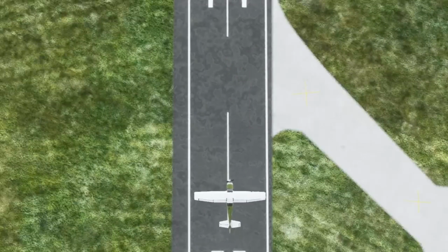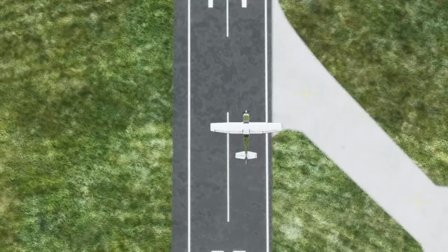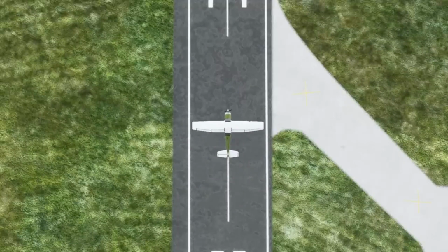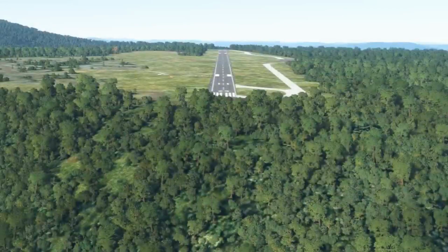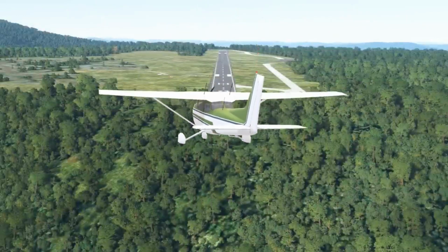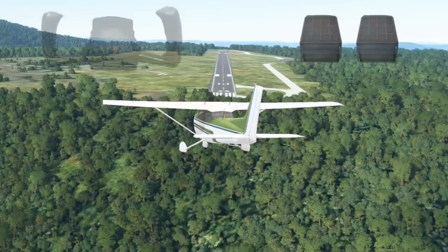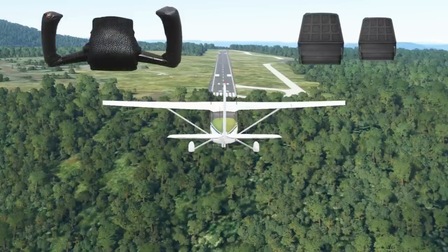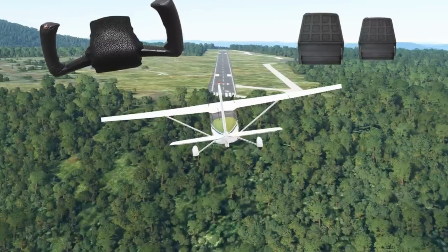Although side load differs in varying tires and air pressures, it is completely independent of speed, and through a considerable range, is directly proportional to the cornering angle and the weight supported by the tire. As little as 10 degrees of cornering angle creates a side load equal to half the supported weight. After 20 degrees, the side load does not increase with increasing cornering angle. For each high-wing, tricycle-geared airplane, there is a cornering angle at which rollover is inevitable. At lesser angles, the rollover may be avoided by use of ailerons, rudder, or steerable nosewheel, but not brakes.